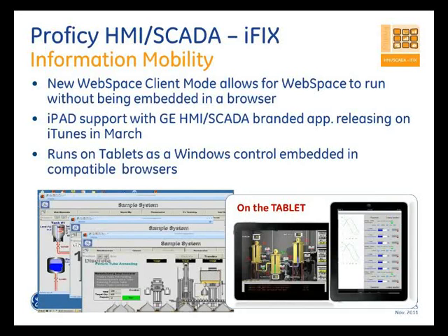Again, WebSpace with iFIX 5.5 only supports Windows 7 64-bit. As far as 2008 is concerned, you can use 32 or 64. But from a Windows 7 perspective, the server side only supports running on a 64-bit OS. On the client side, you can have a 32-bit or a 64-bit OS that you run Windows 7 on, but from a server standpoint, you have to have the server on a 64-bit OS.